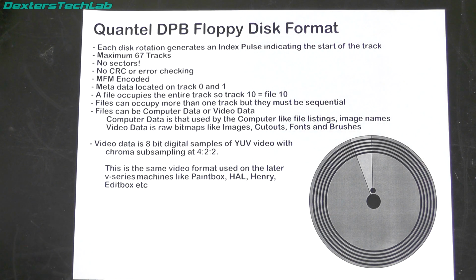Now the video data is 8-bit digital samples of YUV video with chroma subsampling at 4:2:2. This format is the same as that used on the later Quantel machines like the V-Series, Paintbox, HAL, Editbox, that kind of thing.